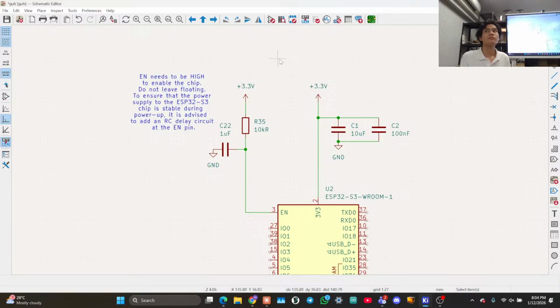Basically, negative doesn't mean ground. Negative doesn't mean ground. All that matters in a circuit is that there's a place of high potential and a place of low potential. Current flows from high potential to low potential, right? Zero potential is whatever I want. So zero potential can be some value, and then both my voltages can be negative. It doesn't matter. All that matters is that one is higher and one is lower.